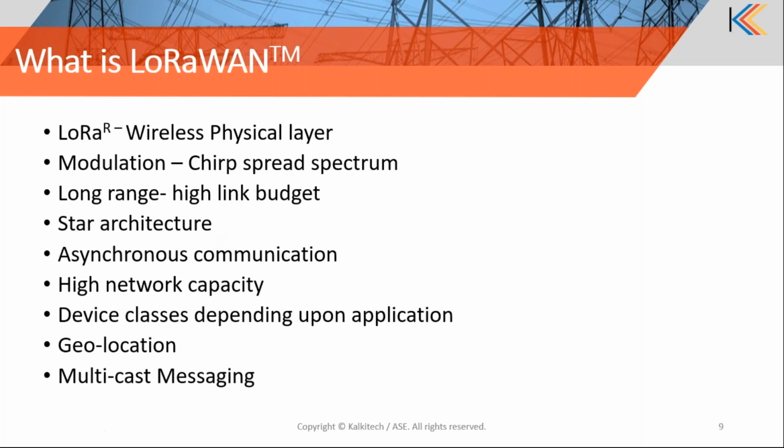So the battery lifetime of each node is preserved to the maximum and used only when necessary, unlike a mesh communication technology. The communications are also asynchronous, meaning each node will communicate with the base stations only when it has to. It could be on an event basis or periodically, but unless there is data to be transferred, there will not be any communication between the nodes and the base stations. That is also a huge advantage in terms of utilizing the bandwidth for other nodes and other data to be transferred over the network. It also has a high penetration rate compared to other wireless technologies.